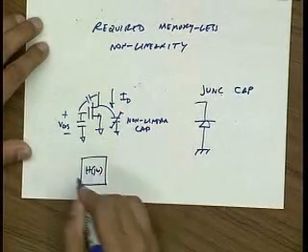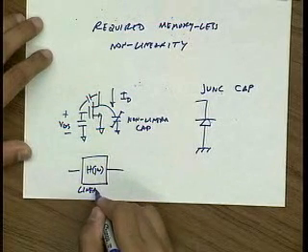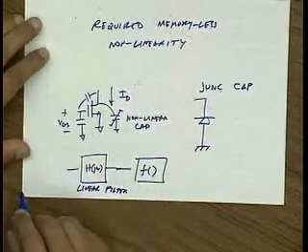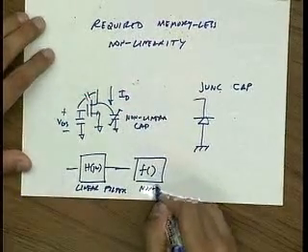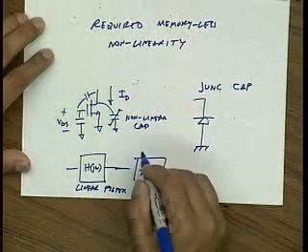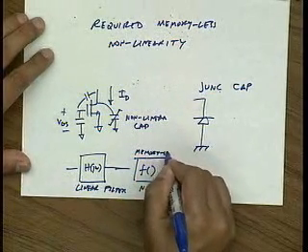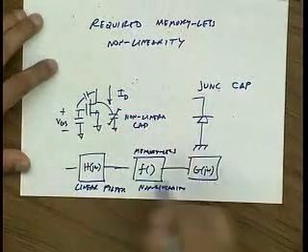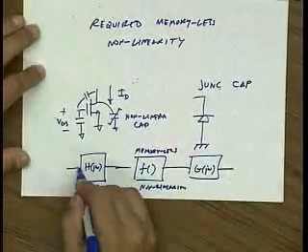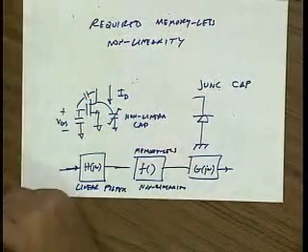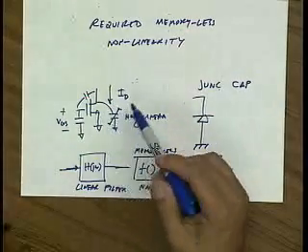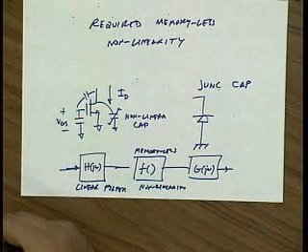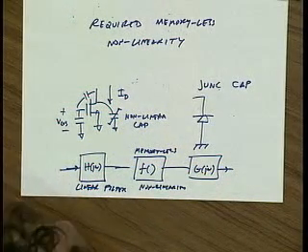So with the exception of this junction capacitance, I can think of this as some linear filter and then some nonlinearity, which is memoryless. And then again at the output I have a pole, so I have another filter, let's say. So it seems like the techniques that we've developed, if we ignore this nonlinear capacitor, can still be applied to even a circuit that has frequency dependence. And in particular, if you're careful, you can just do this by inspection.